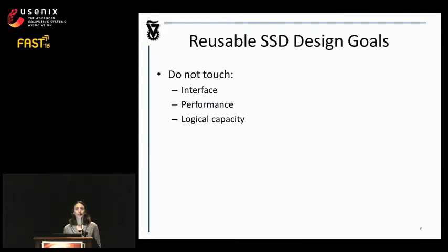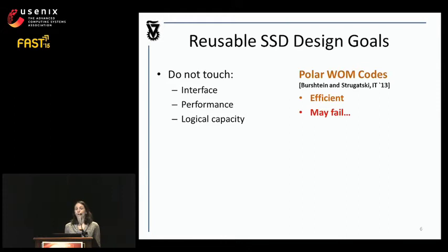So our design of reusable SSD is based on 3 observations. There are 3 things that you do not want to touch when you apply WOM codes to Flash. You do not want to change the interface between the SSD and the operating system. You do not want to harm performance in any way, and you do not want to change the logical capacity that's observable by the user.